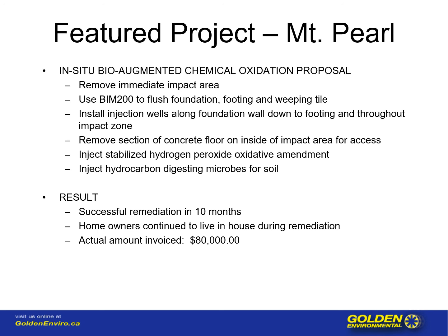One of the reasons that stabilized hydrogen peroxide was used was the high hydraulic conductivity in this soil. The overburden consisted of large pieces of gravel, some large stones, very loose soils, and it was sitting on top of the bedrock. The oil in this particular situation had gone straight down, and there was very little lateral dispersement. Therefore, with such types of hydraulic conductivity, we need an oxidant that is going to react very quickly as it is moving through the subsurface.